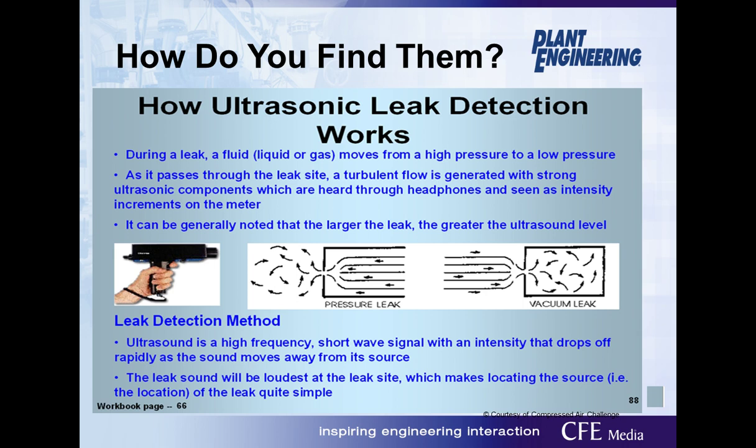And they had a video in the beginning of this, which shows exactly what it is. But again, this is a slide from the Compressed Air Challenge, going through and showing how it works. They mentioned that in the video, but just as a reminder, it really is ultrasonic high-frequency waves, and the short wave signal goes through and drops off quickly. So the closer you are to the leak, the higher the signal is.